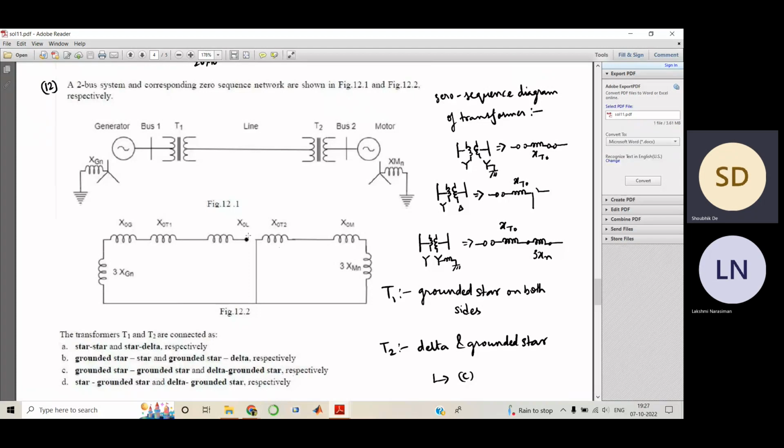Because if this would have been connected, with everything star, you would have a certain magnitude of impedance, right? Because this would have been a closed circuit with a fault at one end, so you would have got some impedance. But now since this side is open, this makes only this closed circuit, so we would have a very small impedance, right?